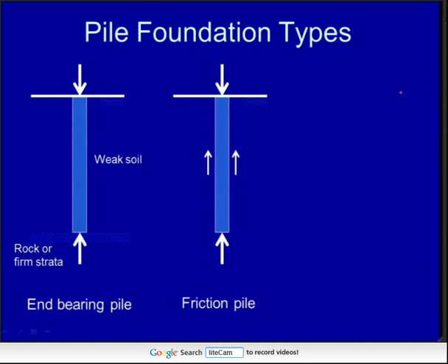The only thing about that is it tends to leave a coating of the drilling mud around the shaft of the hole. And the friction of the drilling mud is lower than the soil usually. So if you're out on site and you've got some bored piles and the construction team are having trouble supporting the hole during construction, you don't want them just choosing to use drilling mud without first speaking to the design team, because if you reduce the friction on the shaft of the pile, you reduce the capacity.